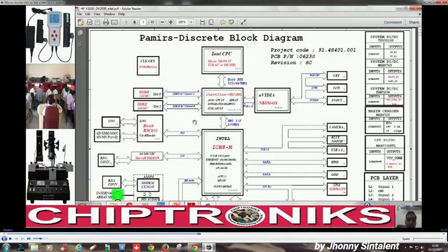So it cannot be considered a case of lumped circuit. Lumped circuit is considered where you can consider the voltages from here to here as the same, but we cannot consider the voltages to be the same when the data communication is taking place at a very high frequency.